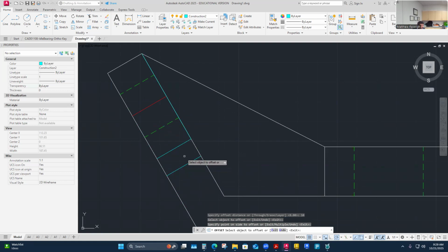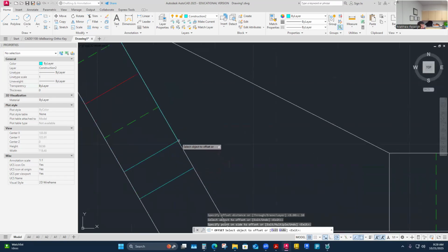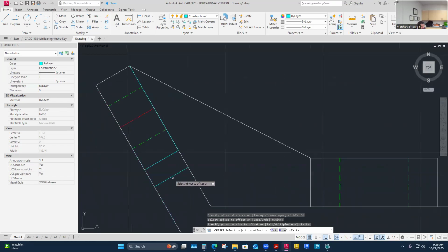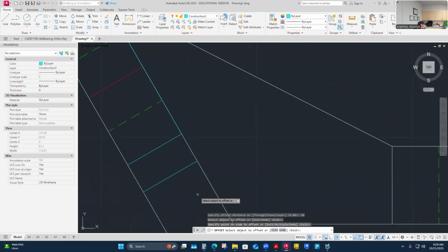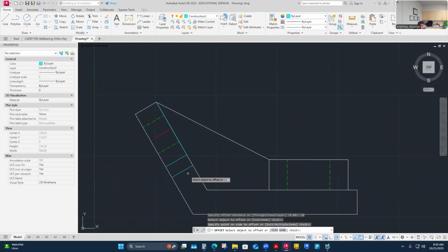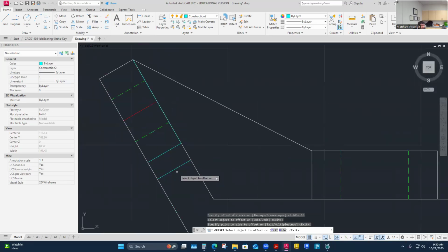So now I'm just trying to make sense out of what I'm seeing here. They're radius features, but those are their true lengths. I would see that radius at its true length right here, that it would measure 10. And so I'm not going to make these visible lines. Sometimes we have shown the extents of that radius, where the surfaces blend together. I'm just going to use them for projection material and not use them for actual visible lines.